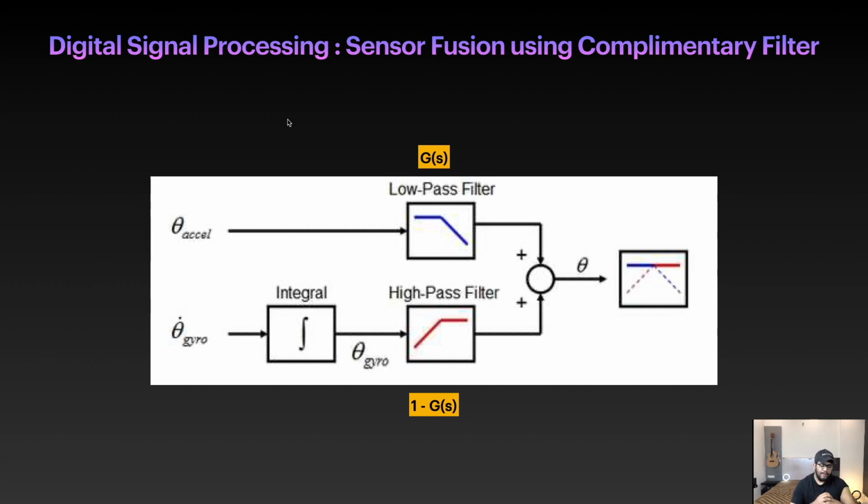Alright, so that was a complementary filter, but do you really see some disadvantage going on here, which is quite significant, especially if you consider that you are getting data at a speed of 32 kilohertz, that is 32,000 values per second? One thing I can definitely see right away is that the complementary filter is using old values and integrating them over time. So over time, a lot of different values will be integrated together, and you need to store these old values, and it becomes really costly on memory and computation power to integrate it and do all kinds of things. That is one drawback I see.